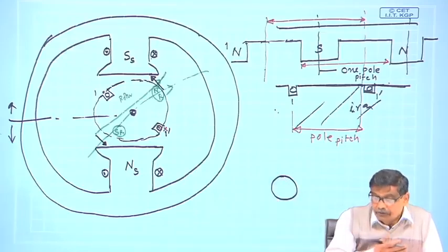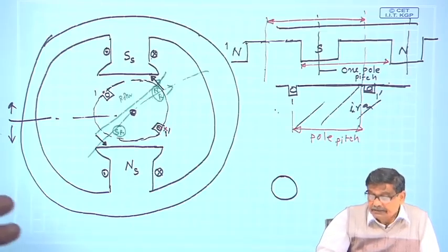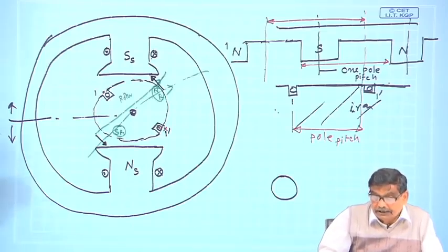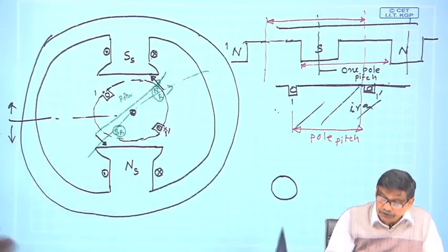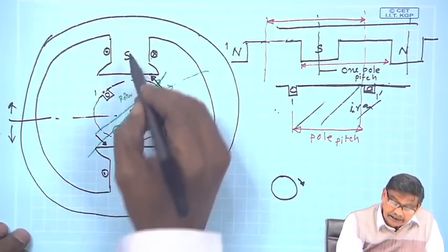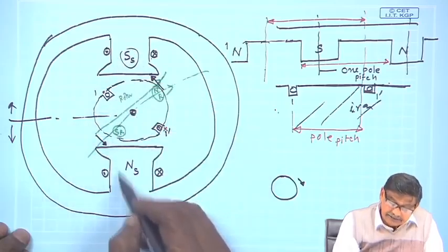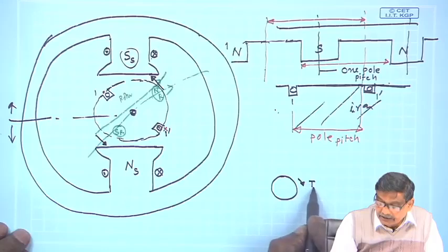I do not know in detail what is inside that motor, but with this argument I can say several things, that NR, SR has been produced, NS, SS has been produced, and it is running at a constant speed, and the interaction of this SS, NS and NR, SR gives you electromagnetic torque.